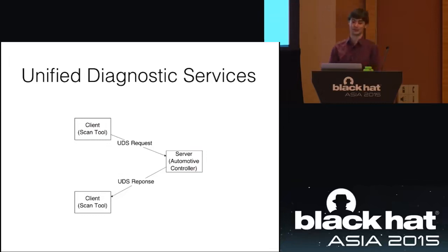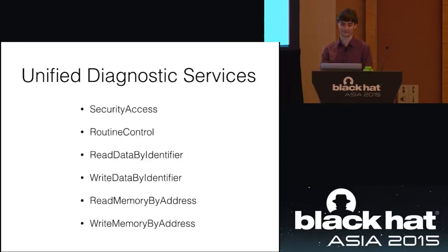It's super simple. You have a client like that tool, you plug it in, it sends a UDS request, and then a server, this is their ISO terminology, the server is that controller, maybe an engine controller, maybe a body controller, maybe a door handle controller if you have a Tesla Model S. And that server will send back a response. That's it. Really simple. All you have to do is figure out how to pack the data, and you can send requests and responses all day.